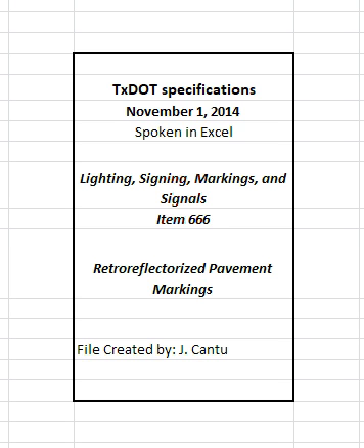The lead vehicle will not be required on divided highways. The TCP and traffic control devices must meet the requirements listed in Item 502, Barricades, Signs, and Traffic Handling. Time restrictions that apply during striping application will also apply during the retroreflectivity inspections except when using the mobile retroreflectometer unless otherwise shown on the plans or approved.